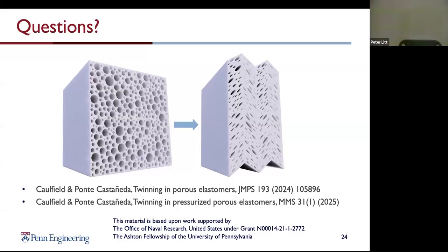In general, you would expect that it would, but in this case, it turns out it doesn't. So when you apply your macroscopic deformation, for any orientation of the layers you can get a configuration which has the same energy and which is rank 1 convex. So if you follow those conditions that I showed for those mesostructural parameters, you get the same energy no matter what, as long as you choose your volume fraction of layers and your deformation to correspond with your orientation of the layers.